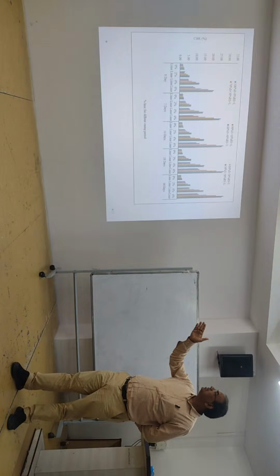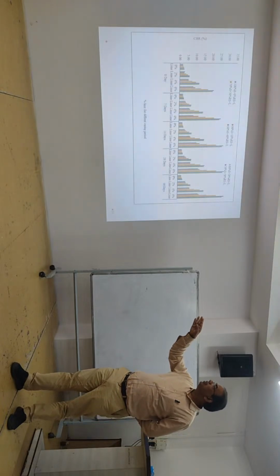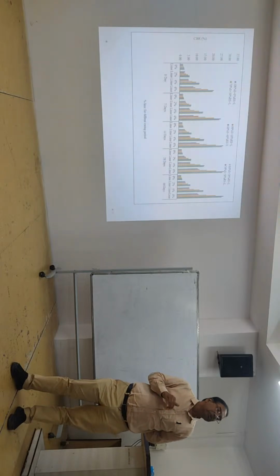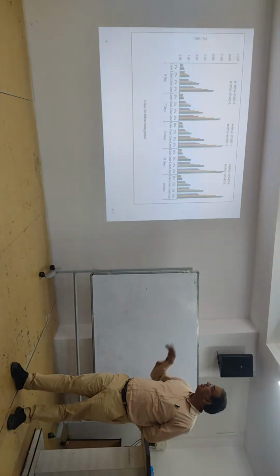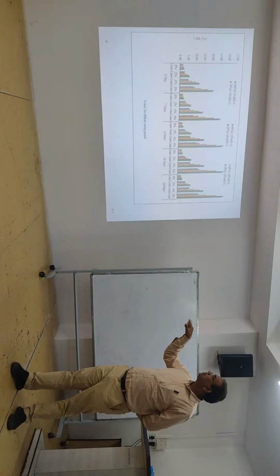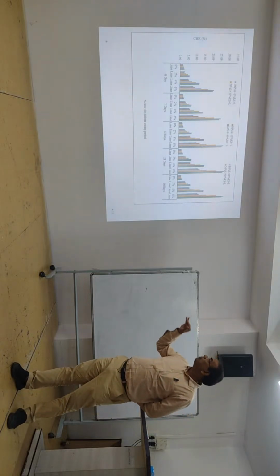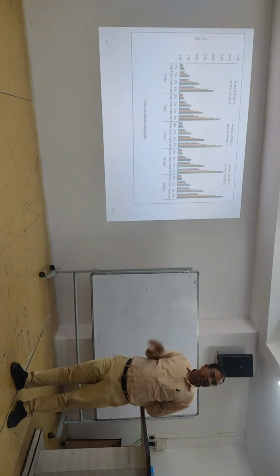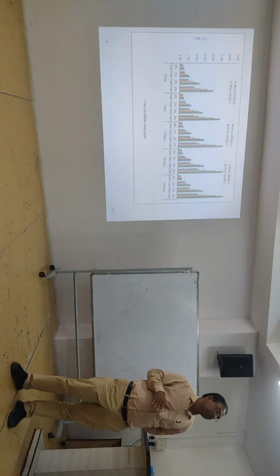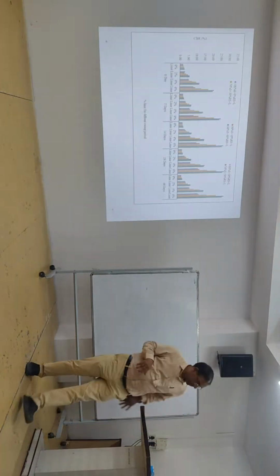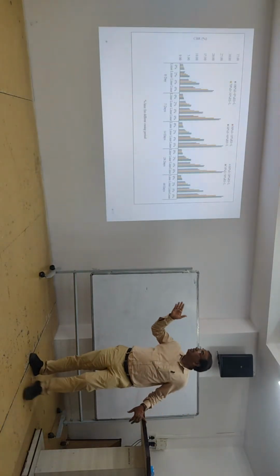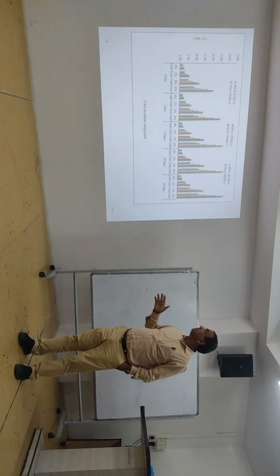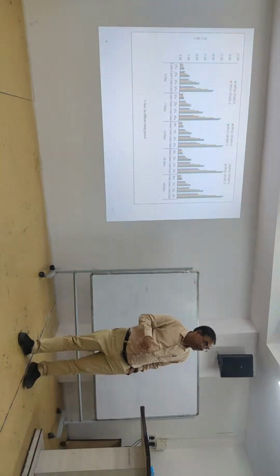So in any case, we require maximum 10% for the CBR, minimum requirement of the road construction of the subgrade. But in all the cases we can see even 4% we can say optimized, 4% we can get, or 6% we can get our requirement for the subgrade road constructions for any national highway. Okay, so we can see that for different combinations we are getting 6%, even 4% also, 8% CBR also will do.